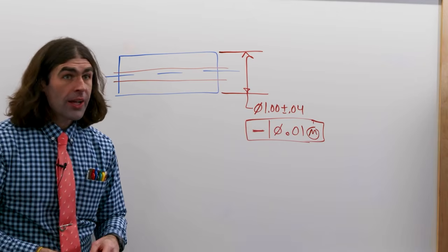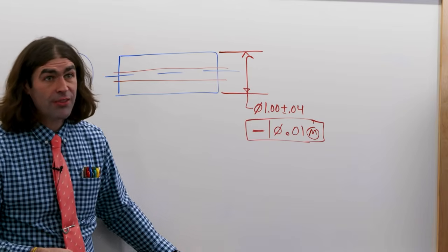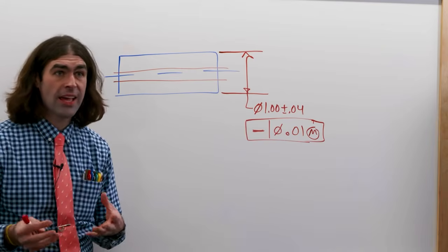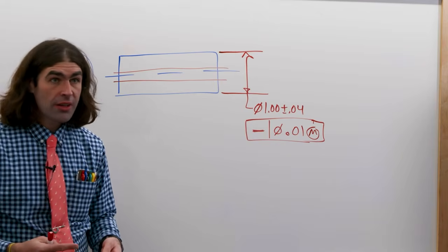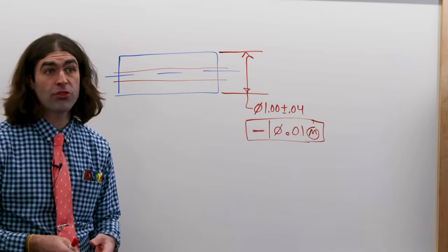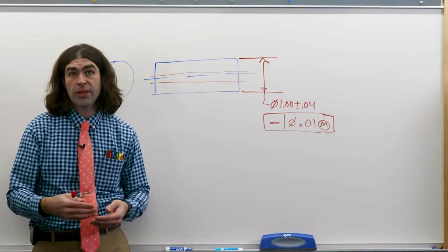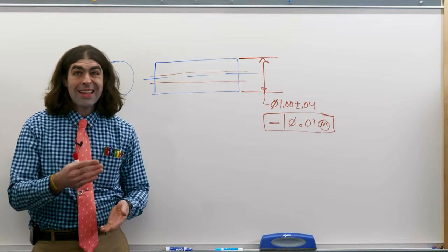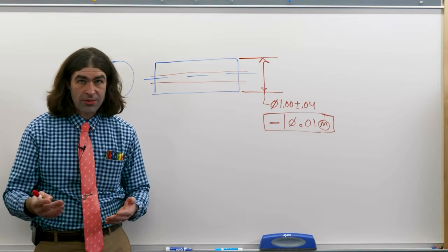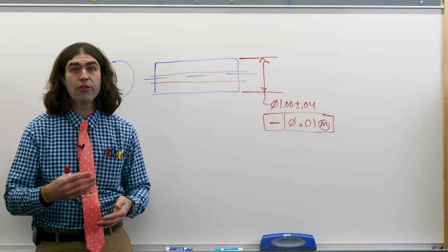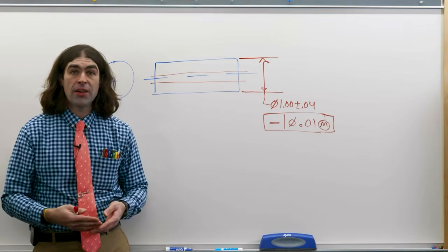The next tolerance we need to look at is flatness. Flatness is extremely common on drawings because a lot of parts are rectangular, and when you use GD&T, you establish datums. Often they're datum planes. Flatness is used to qualify those datums. So if you've seen my other videos, I've said that datums are places to measure from. You want to make sure your datums are good, clear features, right? They don't need giant form variations that can make measuring difficult. So flatness is often applied to datum features so that you have a good place to measure from.